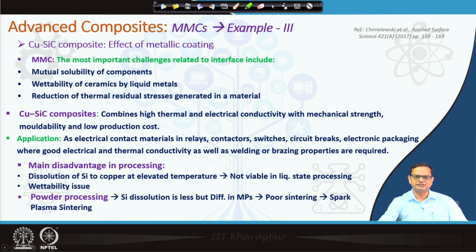Silicon carbide particles were coated with different kinds of metallic thin films, and those metal coated SiC particles were spark plasma sintered with copper particles, and the effect of that metal coating was observed in this particular example. That is the basic point in this case.